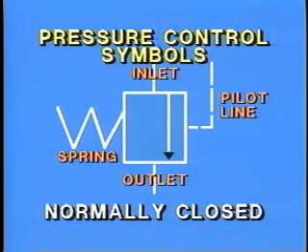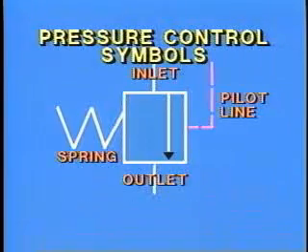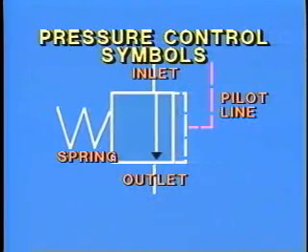Mentally visualize a buildup of pressure in the pilot line and the square moving over, compressing the spring. This would allow oil to flow through the valve. If your visualization was correct, the valve would look like this.